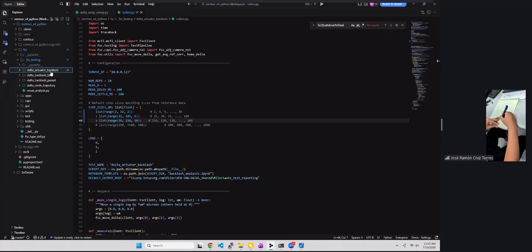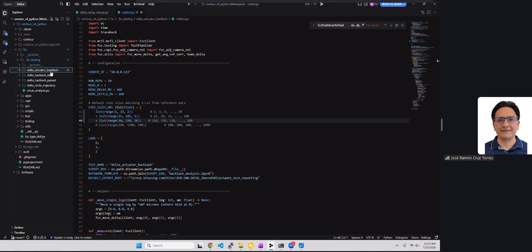Let's just say this is 1,000 microns. You moved this one leg 1,000 microns, and you held all the other legs consistent. Then you moved 100 microns, and then you moved back 100 microns. The output positions of your end effector are completely different, and completely dependent on the history of the moves, whether you did a backwards move or a forwards move. That's how hysteresis shows up in our specific actuator.